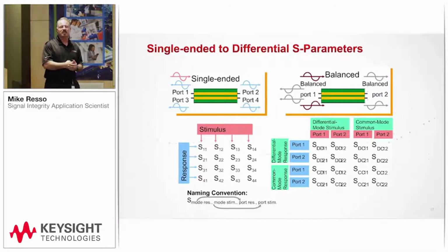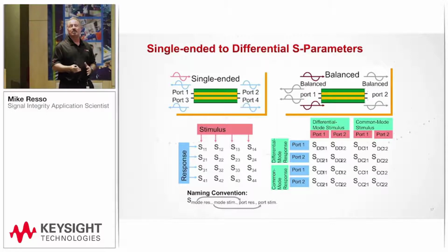They're not single-ended. So you may start in the differential S parameter domain, and you may find a suck out like on one of the channels that Tim saw in the insertion loss. But to troubleshoot, you may want to look at the single-ended parameters because it could be that one of the lines of the differential pair has some type of asymmetry in it, and that could be causing some problems. Maybe not perhaps that suck out, but some other high loss or some crosstalk issues.